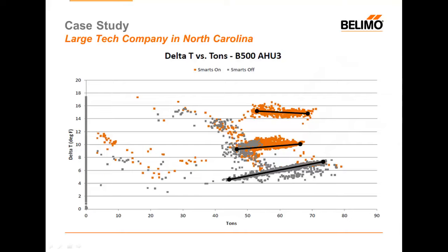This energy valve was installed on an air handler and then operated in 3 different modes over 3 separate time periods. During the first time period, it was operated in position control mode. Position control mode most closely correlates to a standard control valve. That means that the control signal sent to the valve dictates how open or closed the valve orifice is. This is a pressure-dependent function and will have a lot of variation of actual flow.